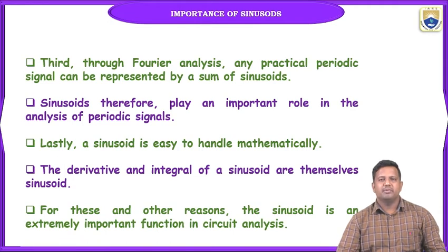We are going to see an important word called impedance, and admittance, of each and every element. For example, if it is an inductor and I want to calculate the impedance of the inductor, that is nothing but J omega L. The J parameter comes into the picture. The omega will come into the picture, omega equal to 2 pi f, so the frequency will come into the picture. If it is a capacitor, the impedance of the capacitor is 1 by J omega C. So again, this impedance of the capacitor involves a complex parameter called the J operator.